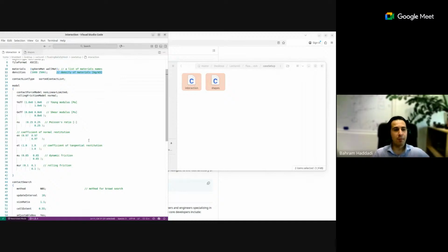The point is that if you want to go into these coefficients in full detail, that will be all on its own lectures and not just a lecture. And what I also need to, I don't want to call it warn you, but make you aware of, is that these coefficients play a quite important role, because by setting them, you are defining how these particles are behaving against each other, how they are repelling each other, how they are sliding next to each other, how they are rotating. So that's quite an important thing. But the bad news is that these coefficients are not that easy to measure. But that's a different topic.